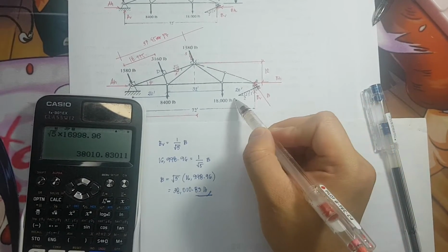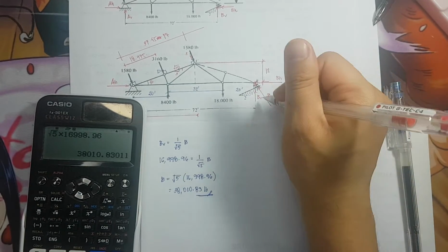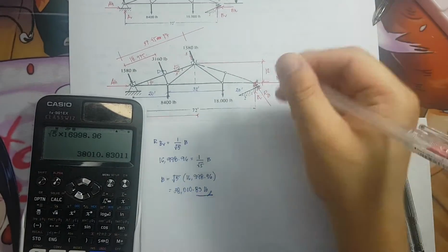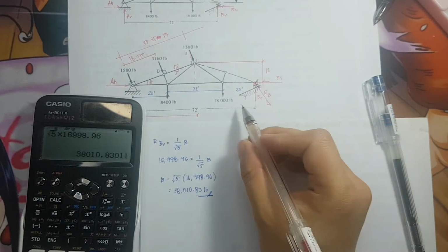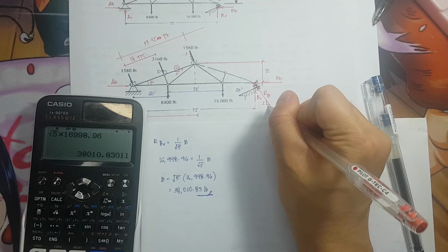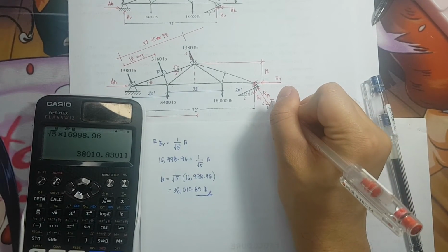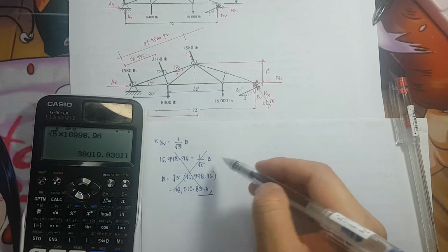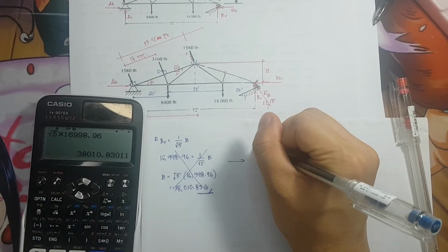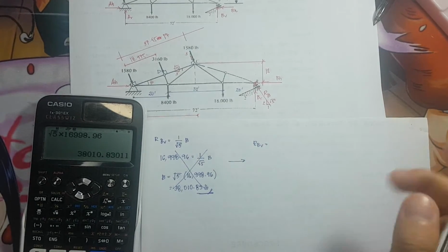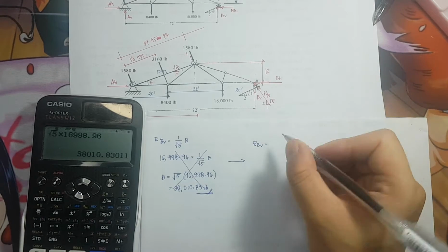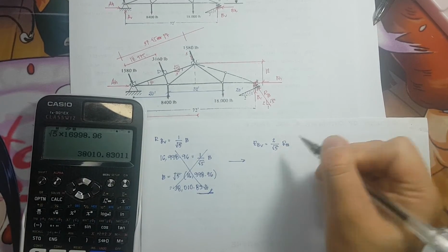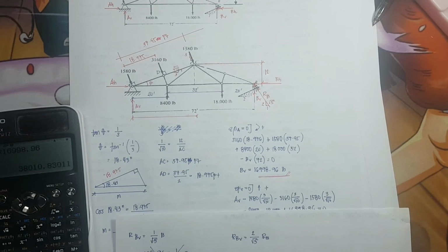Okay, this answer is incorrect because isn't it that the slope of this incline is 2:1? And take note, RB is perpendicular to the slope. Therefore, it will change the slope. So instead of 2 horizontal, it will now become 2 vertical and 1 horizontal. But same for the hypotenuse of the square root of 5. Therefore, instead of having this, we will have this. Okay? So, RB vertical is equivalent to the vertical component of the slope of RB, and that is 2 over the square root of 5 times RB.